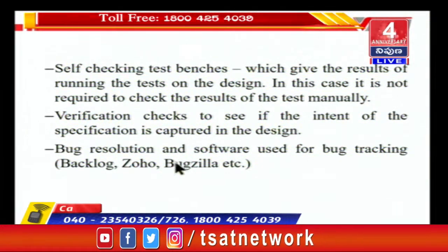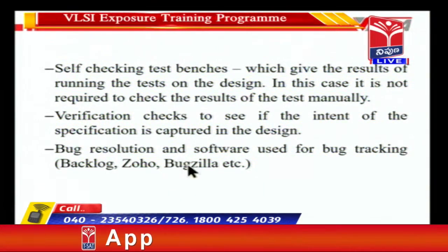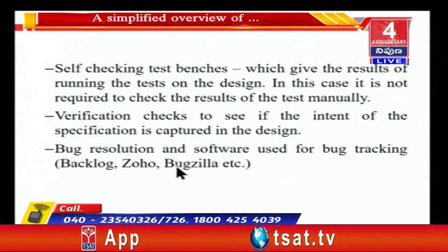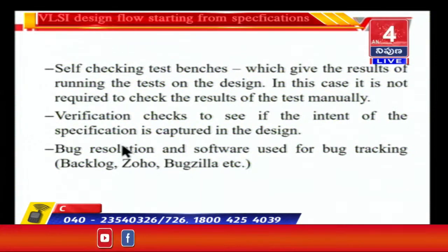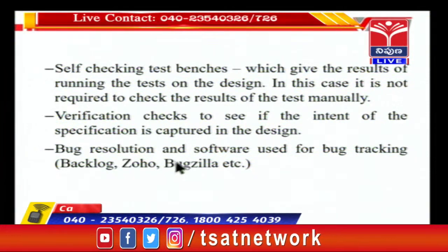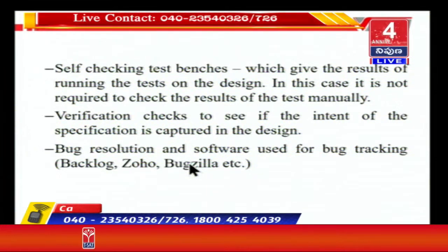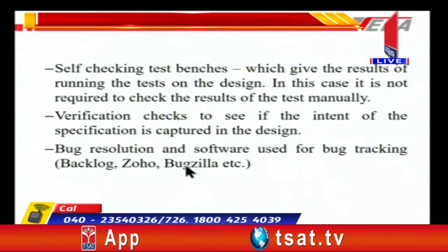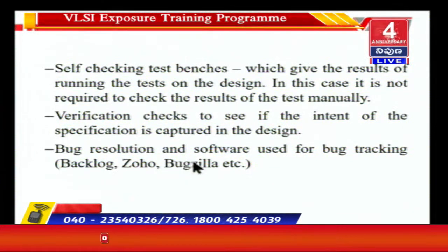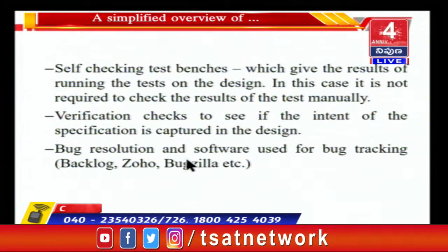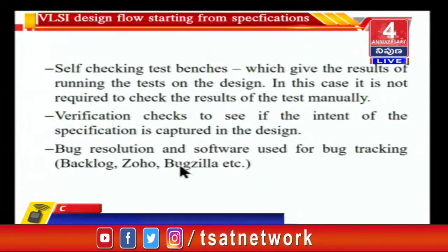Then the verification engineer must also create a test case which shows where the problem is occurring. So the design engineer will take this test case and run it on the design and say whether there is a problem in the design or there is a problem in the test case. Therefore, a test case must be created, or a situation must be created, for the design engineer to handle this bug properly. Once this bug is handled and addressed, the design engineer will put it back to the verification engineer, who only then can close this particular ticket.